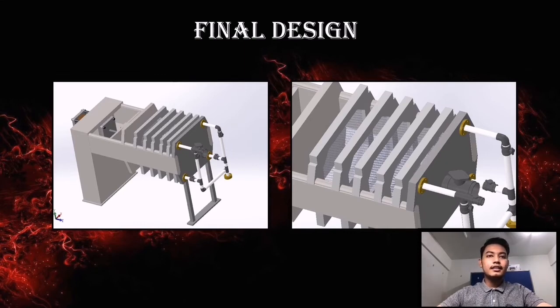Other than that, the advantages of the filter press are high filtration velocity and low moisture content in the filter cakes. Due to the high filtration pressure that can be applied, filter presses have long been used for a wider range of applications than any other type of filter. That's all for me. Thank you.